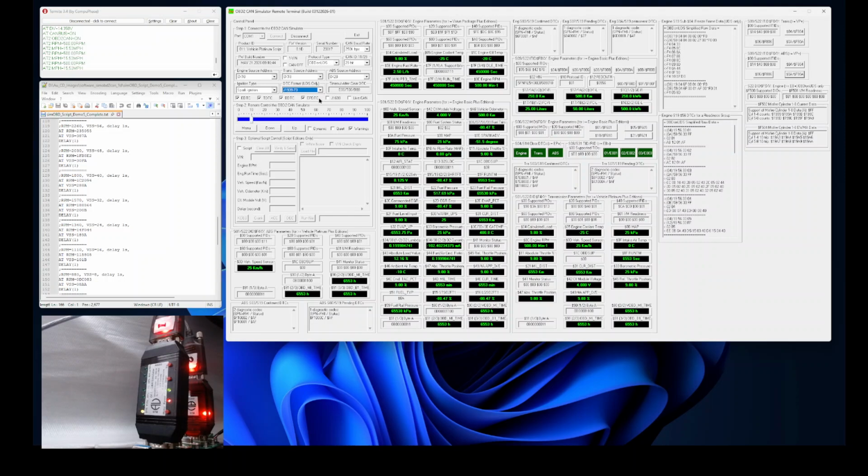Okay, and after that is the warning checkbox. Because we support engine, transmission, and ABS, you can individually control the diagnostic codes, like engine diagnostic, transmission diagnostic, and ABS diagnostic. This one is the engine permanent diagnostic code, and J1699, and you can turn live CAN on or off.